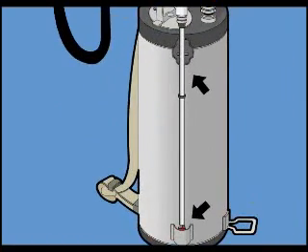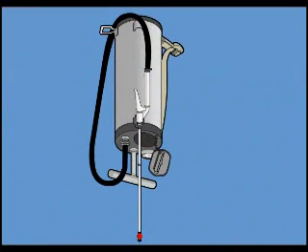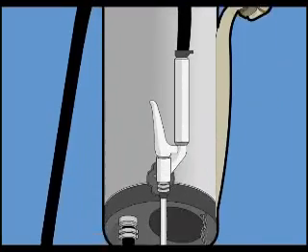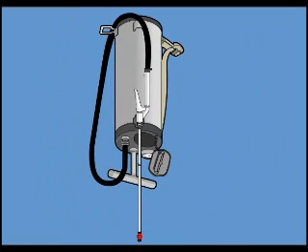Ensure the lance is parked to protect the nozzle when not in use. When storing the sprayer for a long period, hang it upside down with the lid open to allow air circulation. Allow the lance to hang from the D-ring on the tank with the trigger valve cap open.